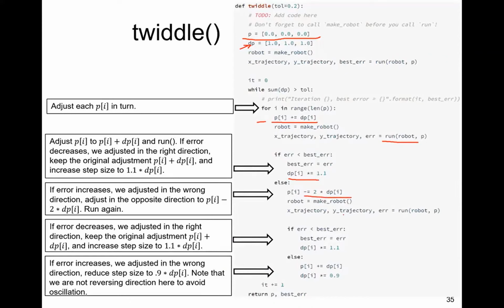And then yes. Can I have a little bit of comment on this as well? Sorry, and that is if you work with control, if you start with a P value, the proportional part, and it works okay. But then when you add an integral part, you have to reduce the proportional part to keep stability in a control system. You can't select the best P with the integral part at 0, because when you increase the integral part, you have to reduce the proportional part.